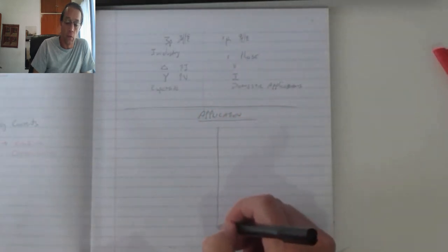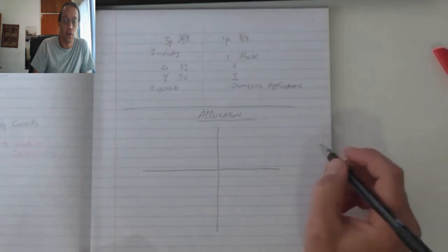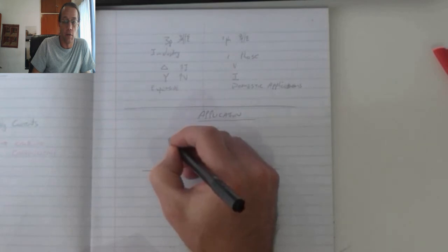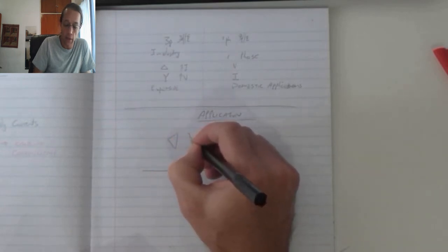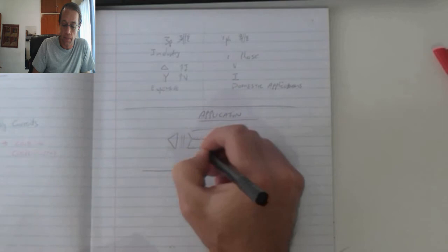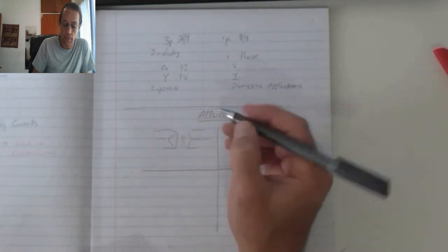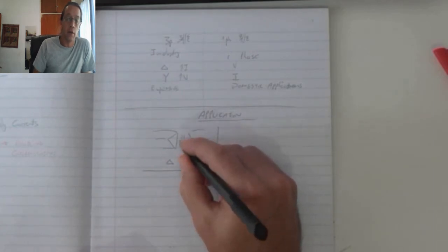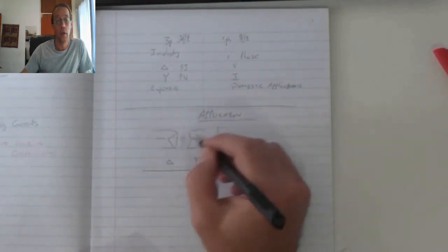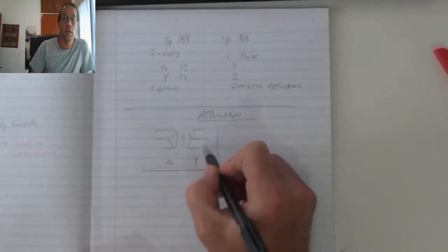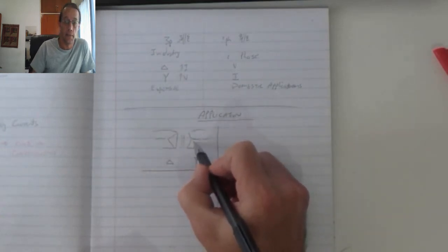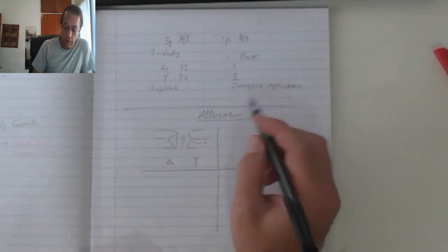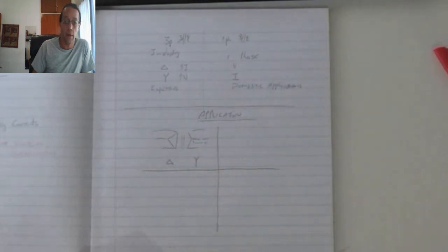We can have four different configurations when it comes to three-phase transformers. First type of configuration is my delta-star configuration. Okay, delta versus star. Delta on the primary, star on the secondary. This is useful in converting a 3-line into a 4-line. Remember, the fourth line is my neutral that we can connect over there. This is used for domestic load purposes.